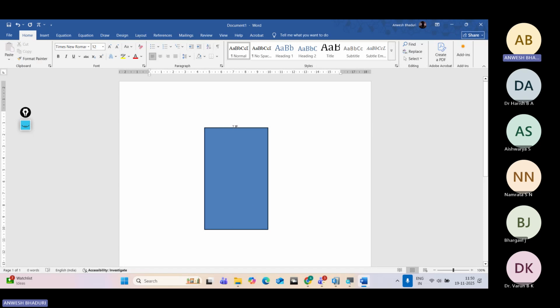So in the top, you have the top center, the top left and the top right. Similarly, at the center, you have center left, centroid, and the center right. And at the bottom, you have the bottom left, bottom center, and the bottom right. So you can join different frame objects through these cardinal points. And if you need to provide some offset, then these offsets will be provided from these cardinal points.